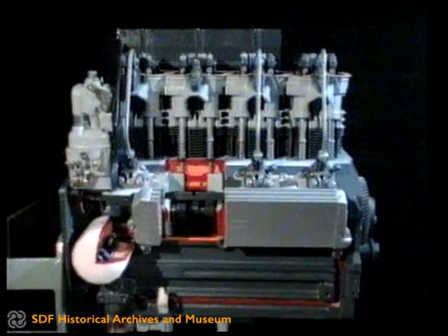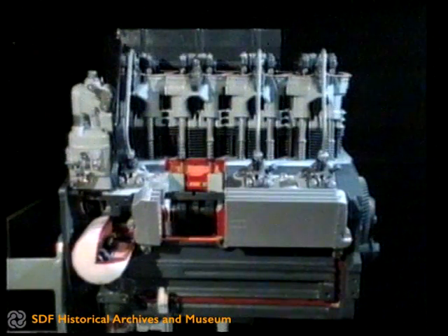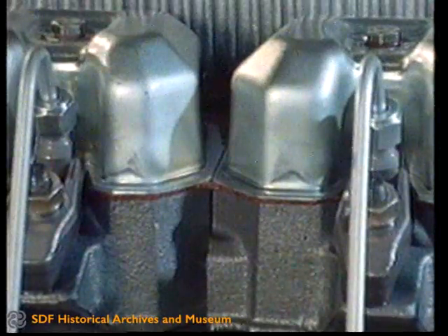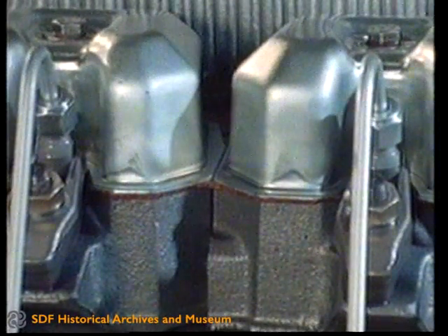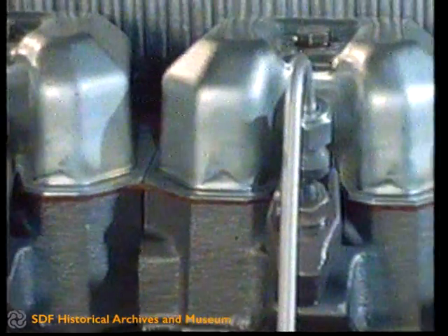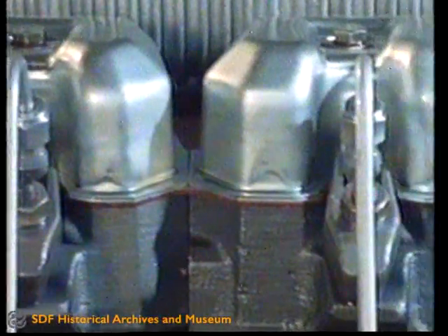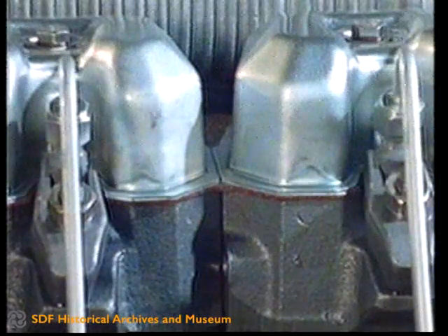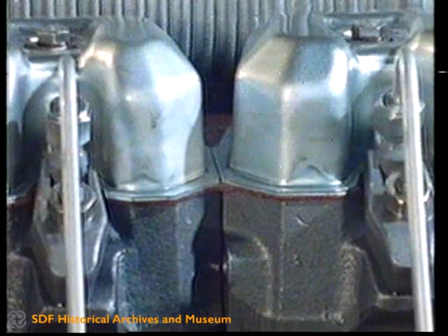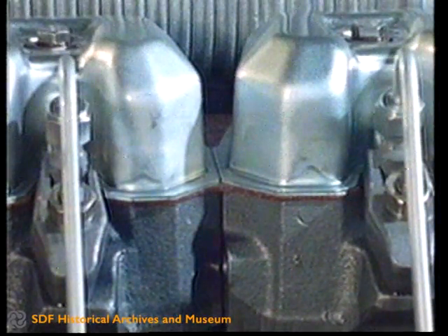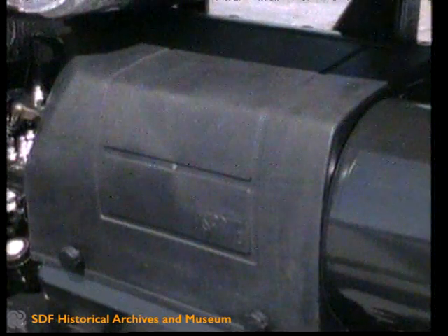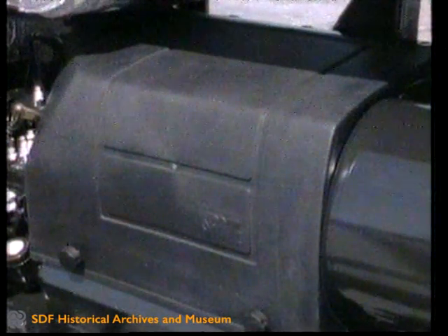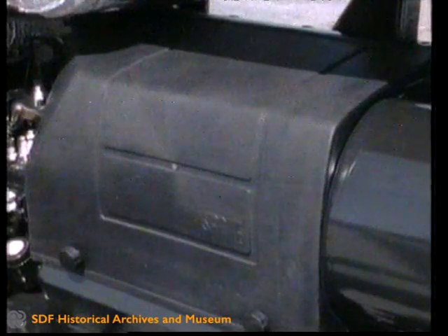Air cooling of the engine has permitted the design of engines with independent heads extremely easily, so that there is improved tightness of the cylinders due to the more precise centering of the heads on the cylinders, reduction of engine servicing times and costs, reduction in costs of parts stocks. Soundproofed air duct. This provides better soundproofing.